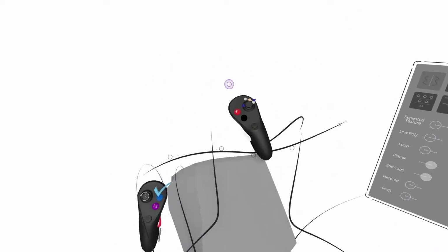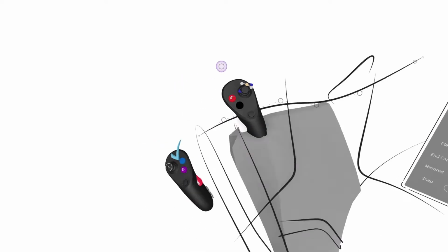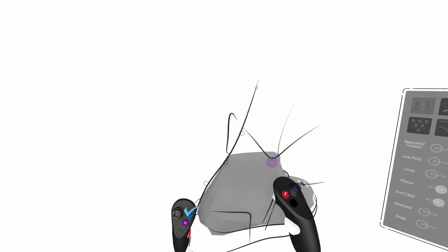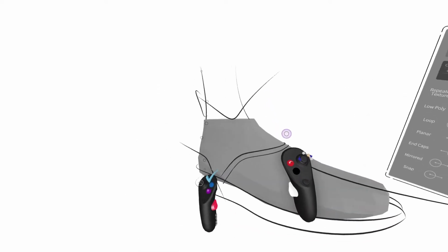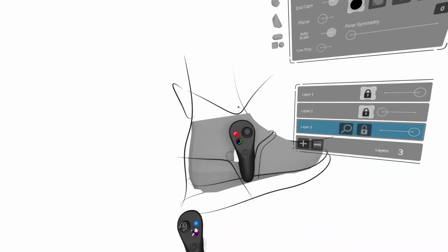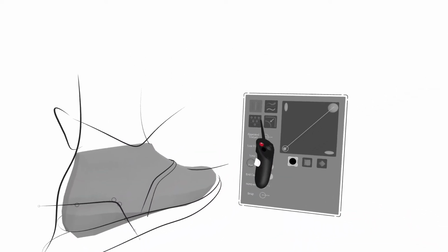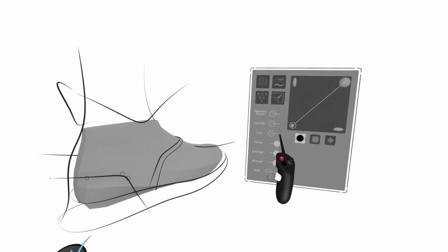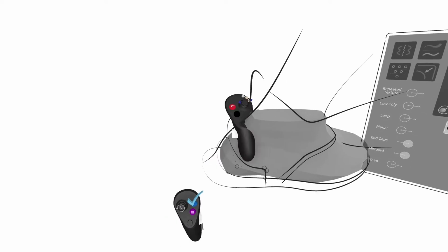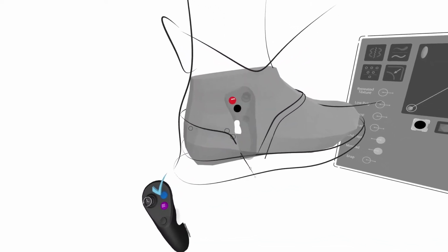But I don't feel comfortable with the heel line, so I'll fix that now. I'm leaving these lines constrained because I think they give a little bit of shape and character to the shoe. So I'm leaving these planar because they're actually giving us the information from the profile perspective. We'll come in here and do the same thing. So I'll mirror this guy and turn off planar, bring this around, tighten this up.